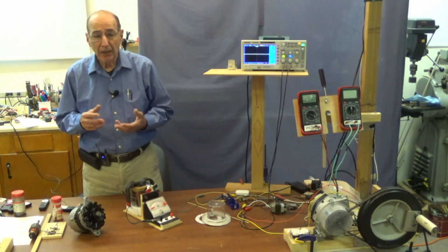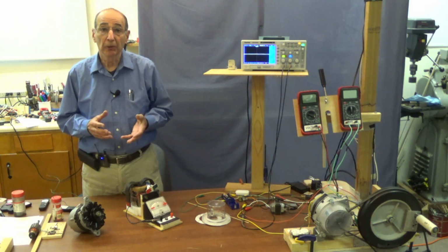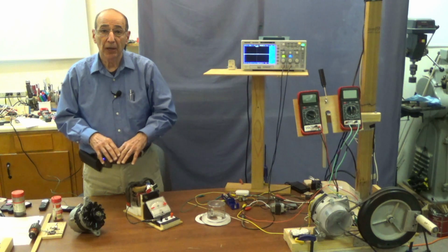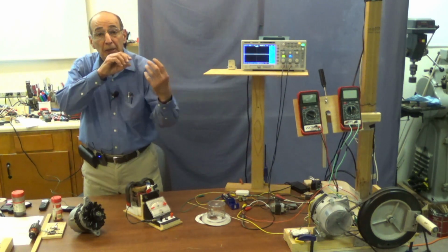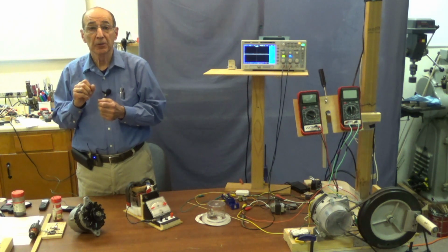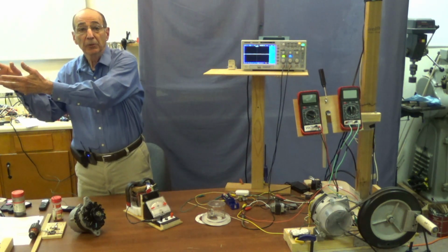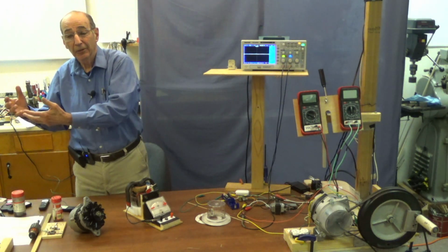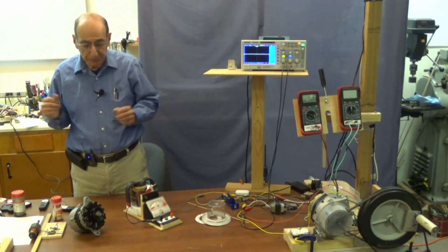Alternating current allows us to use the transformer, which can raise the voltage, lower the amperage, and send the electricity long distance over reasonable sized conductors to another transformer, where we lower the voltage, raise the amperage, and it's a voltage that's safe for us to be near.